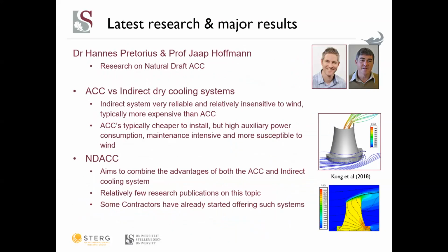So that brings us to myself and Professor Jaap Hofman. We are doing research on natural draft ACCs. When we talk about ACCs and indirect dry cooling systems, the indirect dry system is typically very reliable and relatively insensitive to wind, but typically more expensive than an air-cooled condenser.